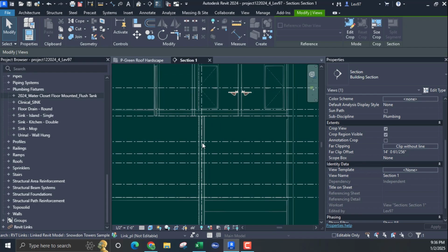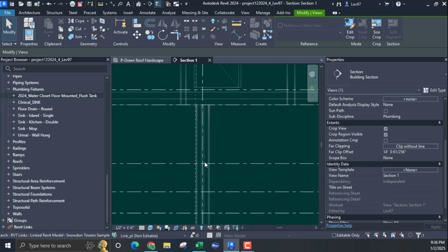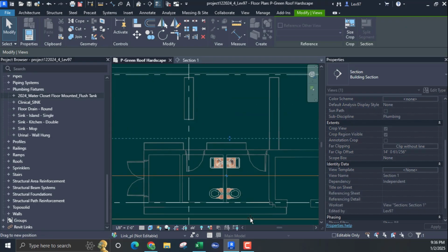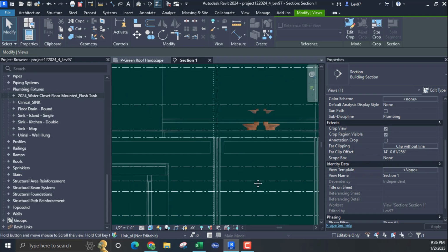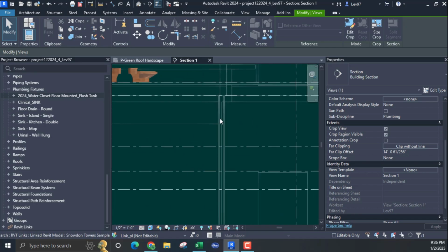Like if that was a nice wall, maybe an 8-inch interior wall, some type of plumbing chase wall, then you could see that might be a nice little cavity we could sneak our pipe down in, okay? But I don't think that there's any, it just doesn't look good, guys. It just doesn't look good. There's nothing out here. That's probably why the plumbing engineer went down this wall, which is what I'm gonna do.